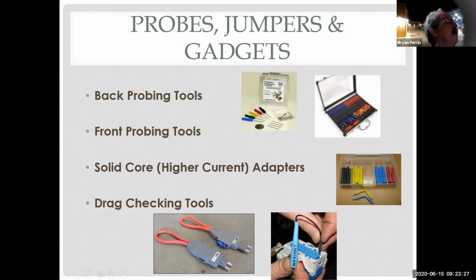And with this tool right here, we're checking to see if the pin is damaged. What happens is, if people use the wrong test equipment, they push something in and it opens the pin up. Then they plug it back in and it no longer makes a good connection, so the circuit won't work. So we use tools for drag testing, which you see there, where you slide it in and it should have enough tension to hold the connector in midair. If it doesn't, the connector is opened up. It's got a problem. And we actually have that problem on one of the trainers in the classroom.